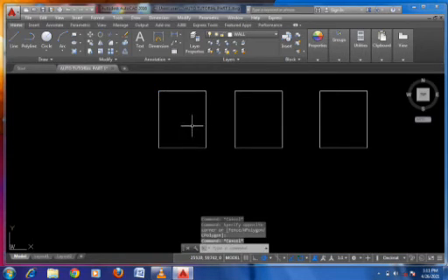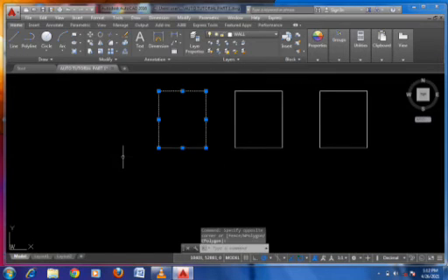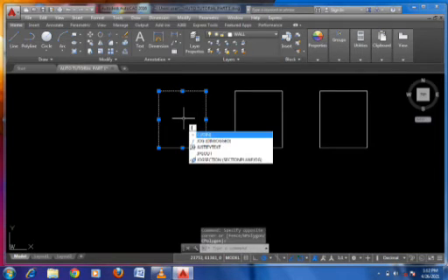And press escape. So I can make my discontinuous line to be in one entity, like the polyline and the rectangle too. So let's highlight all. Now you press J, that is join, J, enter.